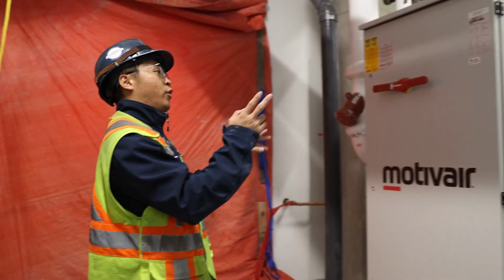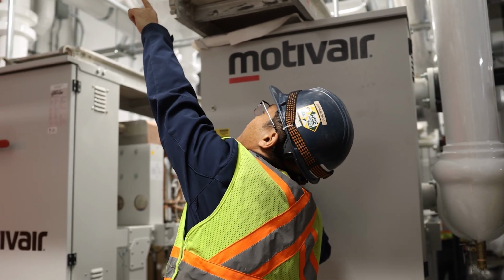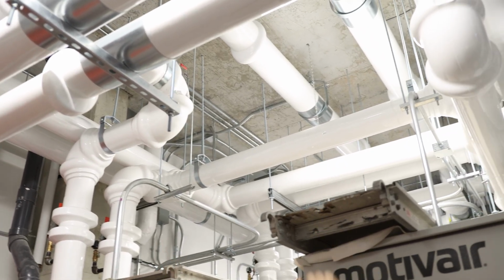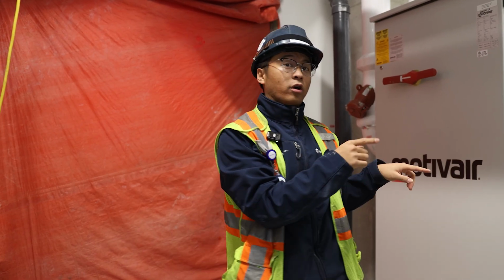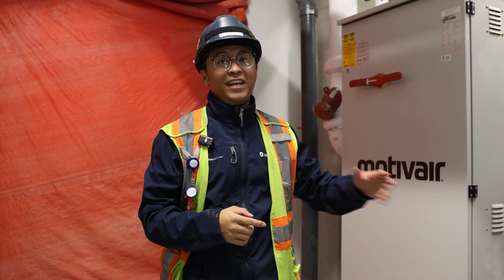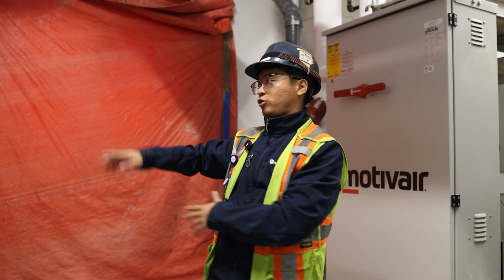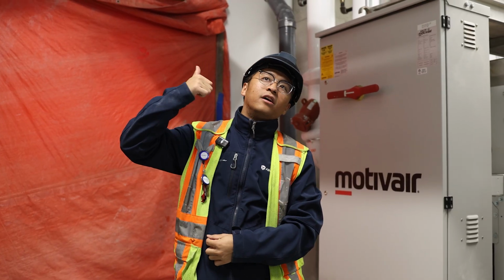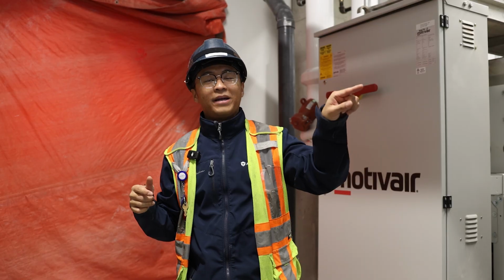And the BMS, on the water-to-water heating side, we will have an isolation valve over there, and another isolation valve there, because if both water-to-water heat pumps are in alarm, and they are not able to provide enough heat to a domestic hot water tank, we will then switch to the boiler loop. So the boiler set point will then increase, then the boiler will be supplying the heat to the domestic hot water